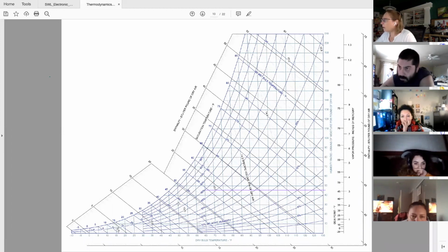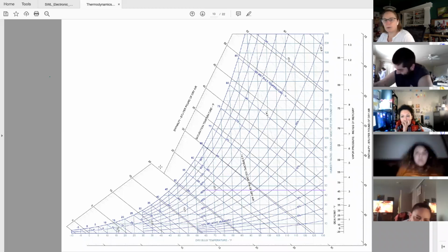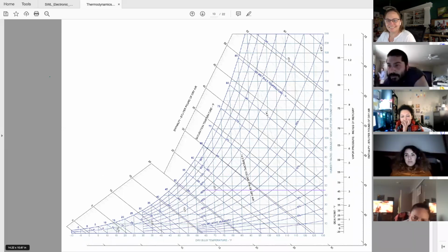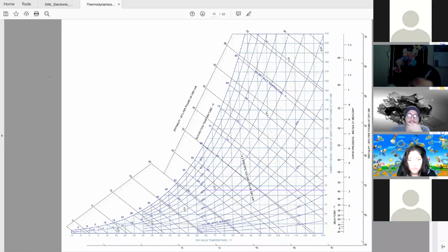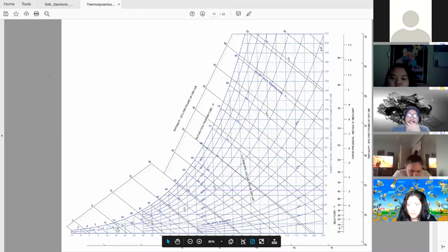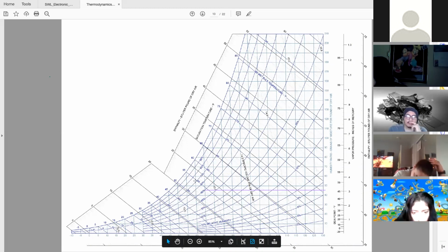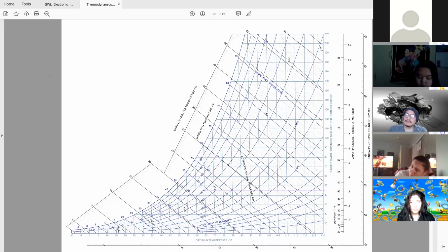Okay, Arturo, for San Diego, you ready? It's 51 to 52 degrees, somewhere in there. Okay, wait a minute. I thought we were doing 72 degrees. No, 61 degrees Fahrenheit, 72% relative humidity. 61 degrees Fahrenheit gives us a saturation temperature of 51 degrees. 52 maybe? It's okay. Oh, yes. You're right.